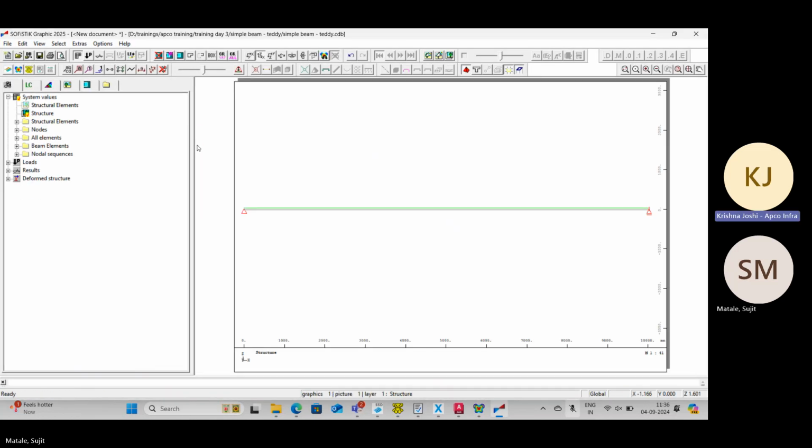You assign factor for dead load. You are assigning factor 1 for dead load. You can assign factor 5 for dead load. So it's not 0 or 1. 0 means not assigned, 1 means assigned. It's not that. You assign a factor, and it could be any number.